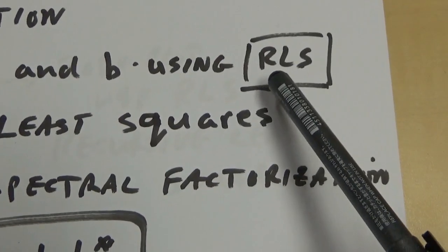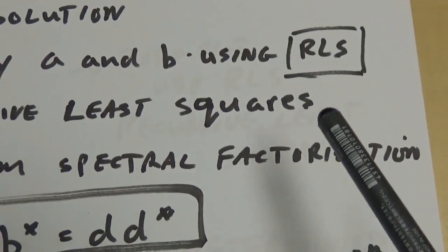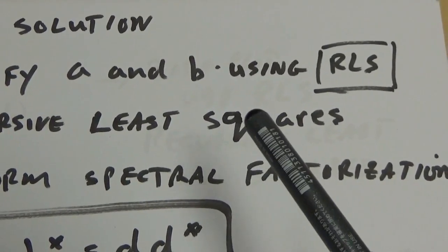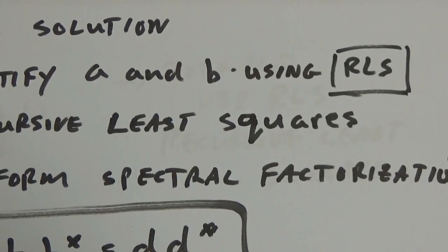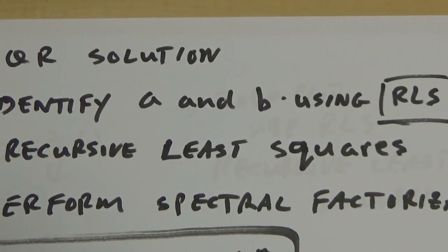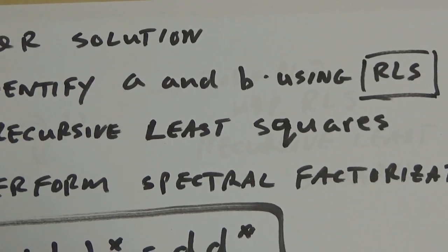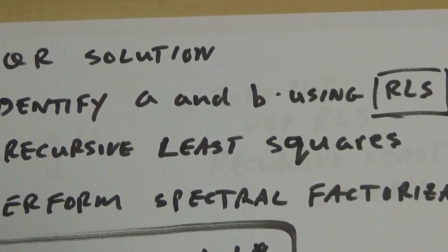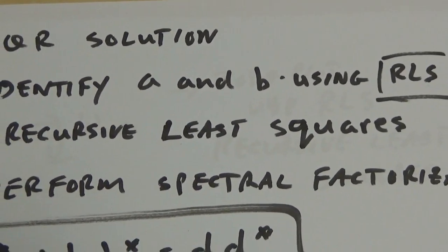This itself has problems. Usually the system has to be persistently exciting, which means the input to the system needs to be rich in harmonics, and in textbooks this usually means putting in white noise. And although we can do that, we'll just use a square wave to achieve a similar goal.